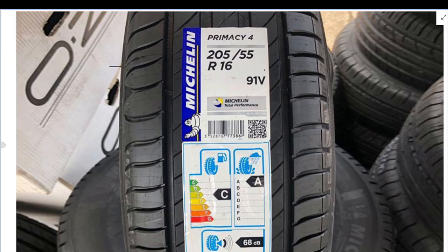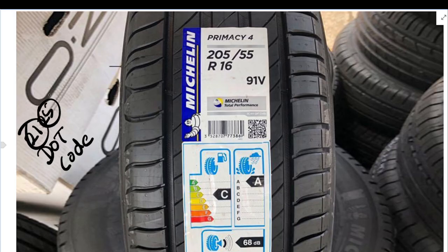First, you will look for the manufacturing date, which is normally written on the sidewall as the DOT code, as I explained previously. You have a four-digit number with the week number and the year number, for example 21 and 25, as we saw. Ideally, we prefer a tire that is less than 5 years old. Otherwise, it is going to be more oxidized and weathered, which will reduce the tire's life.